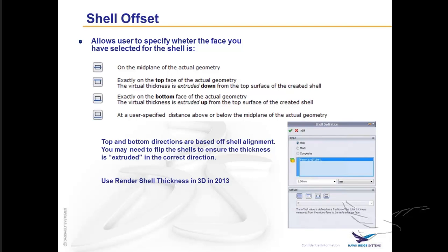And sometimes it's not very handy to create a mid-surface model. Maybe you just have the outer face or the inner face. So you can create a shell using the outer face of your solid model or the inner face of your solid model. And in an effort to try and get the shell to lie at the midplane, we can use a shell offset here. And the shell offset